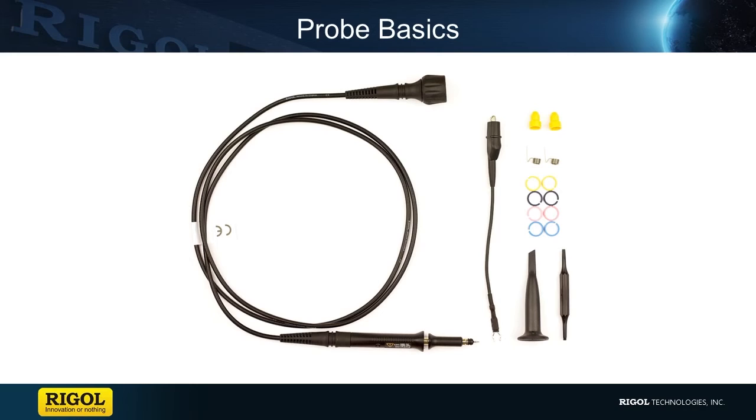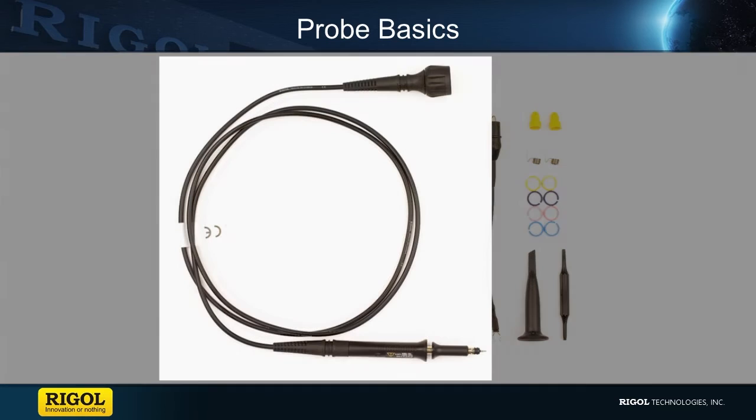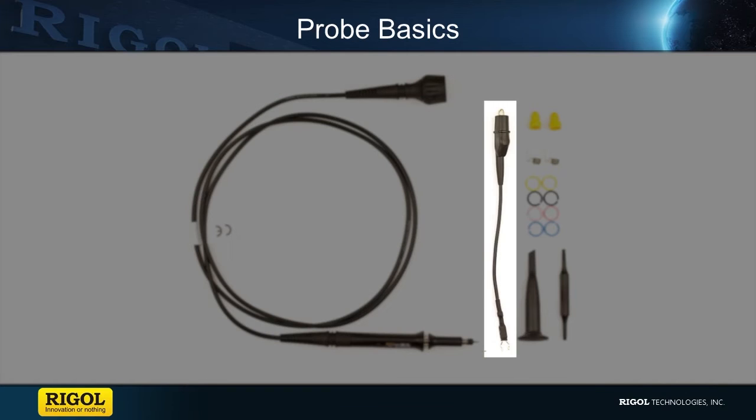I will be covering our basic probe set and different items that are shipped along with our passive probes. To begin with, the probe kit comes with the probe, which for this model has an attenuation switch to switch between 1 times and 10 times. There's a compensation screw to adjust the probe's compensation. There's an alligator ground clip used to ensure a safe common ground.